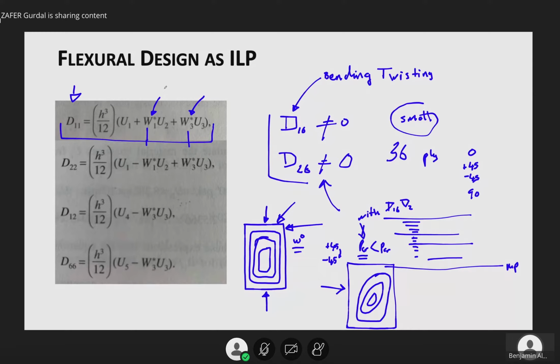These are zeros and ones, and we're going to enforce only one of those ply orientations to appear in a given location, not allowing the other orientations to be in the same place, so that we can actually start using these linear design variables in the stacking sequence design, so that you can get a nice stacking sequence distribution through the thickness with all these plies that you may be defining. Even if it's 36 of them, you'll be able to define them very nicely. But there will be increased number of variables.